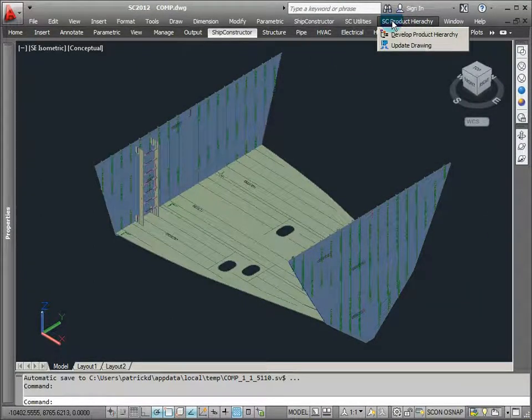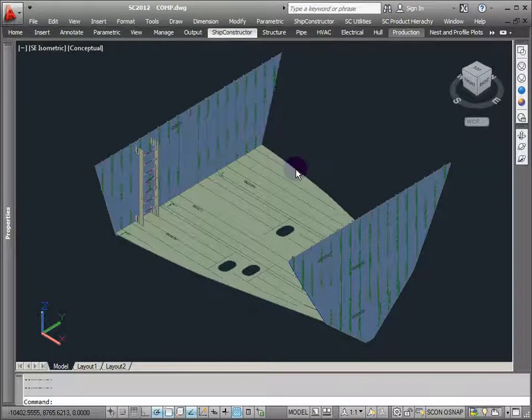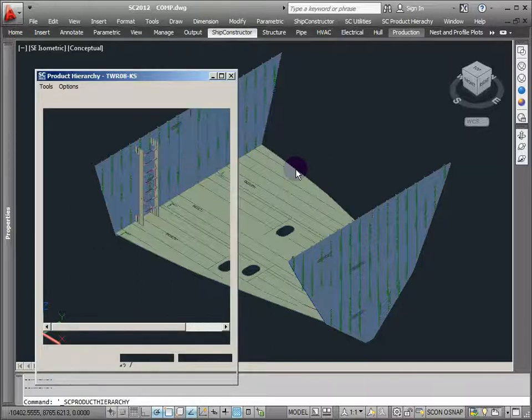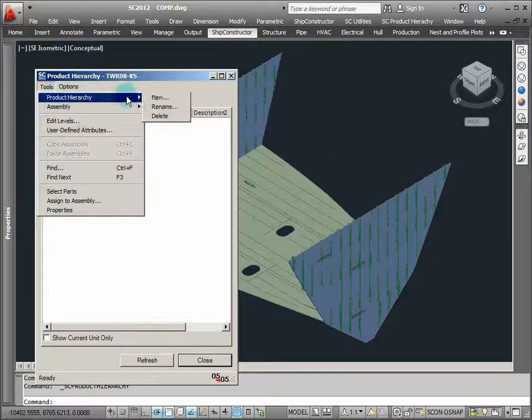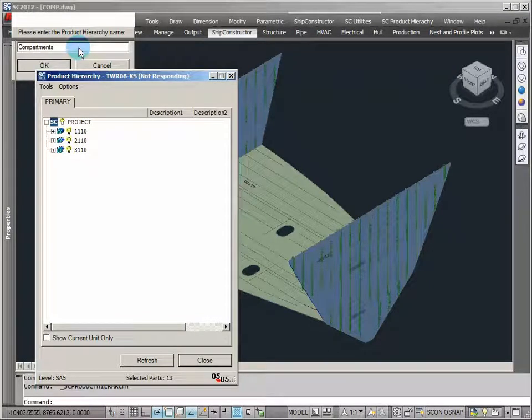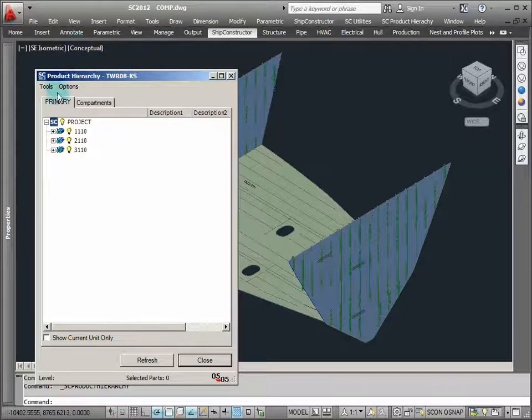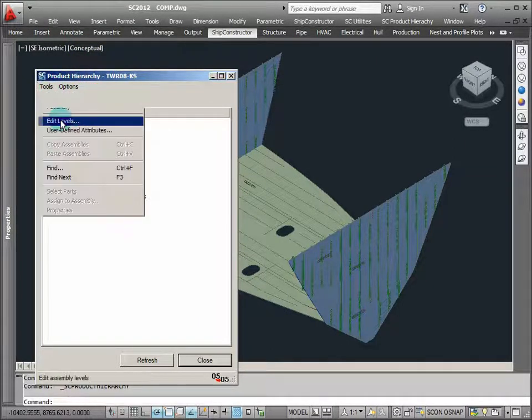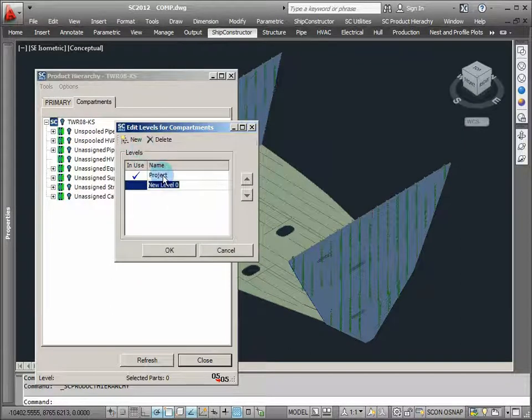figured something out. I said, well, part views is neat because I can load up all the parts in a ShipCon project by volume. And I'm constantly being hammered by Navy program shipbuilders to say, well, what are all the parts that are in a compartment? ShipConstructor doesn't know what a compartment is. We do build sequencing for production staging. I know to install a part on a deck at some point, but I can't tell you these are all the parts that exist in this space until now. Now I can.